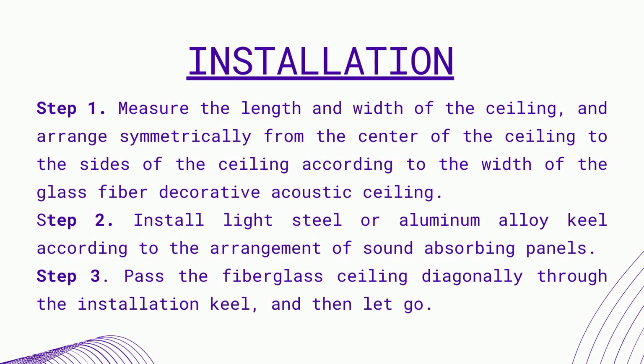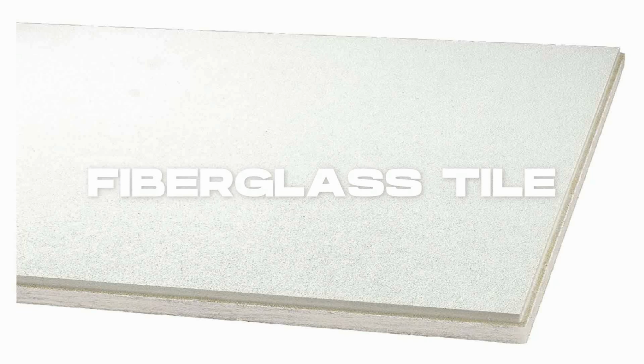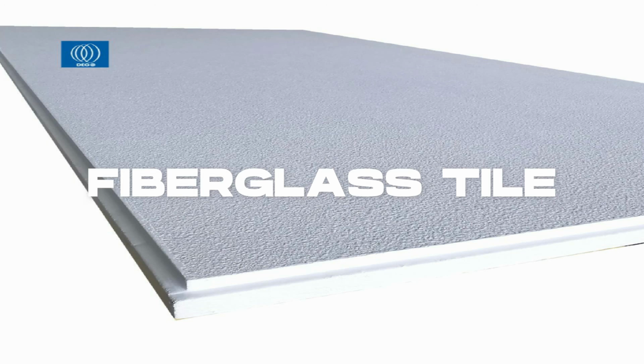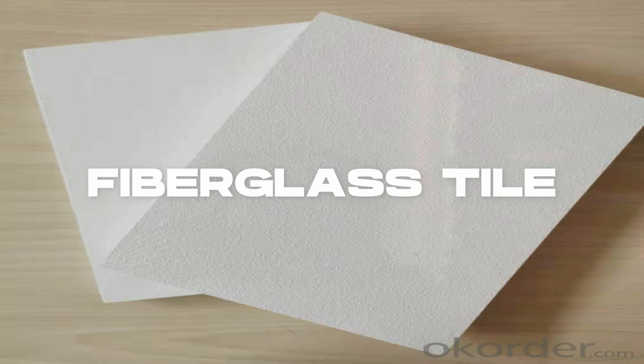The properties of fiberglass tiles are superior thermal and sound absorption properties, manufactured from high-density, third-generation glass wool, non-sensitive, lightweight, and without sagging, warping or delaminating, moisture-resistant, and fire-resistant. The thickness of this finish is usually from 1/16 to 1/2 inches.